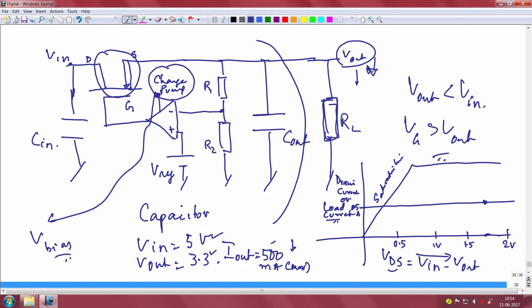So here you have a situation where the requirement is that you have 1.7, and this actually corresponds to the drop, which is 1.7 V, and the maximum current, which is 500 milliamperes. What you should actually know at this point is what the VGS is for this point to remain.